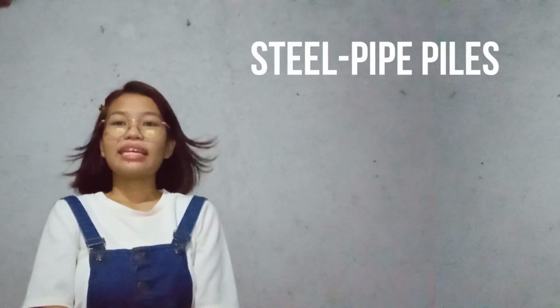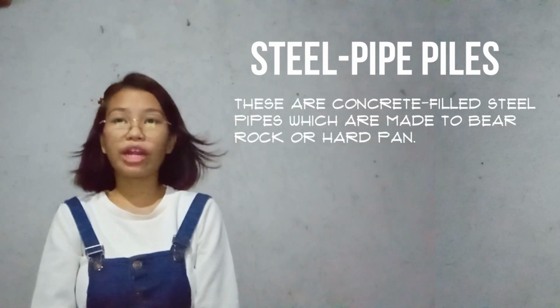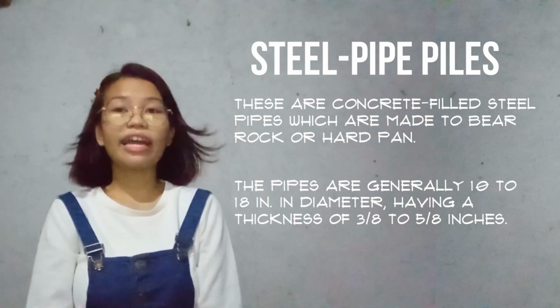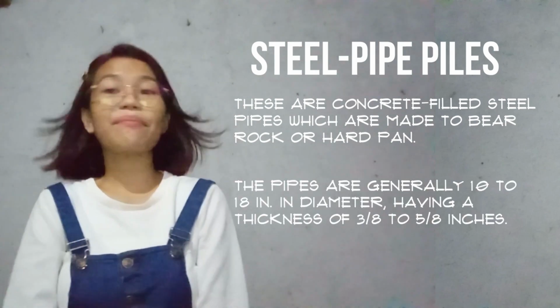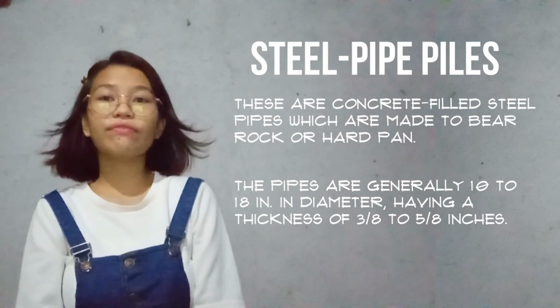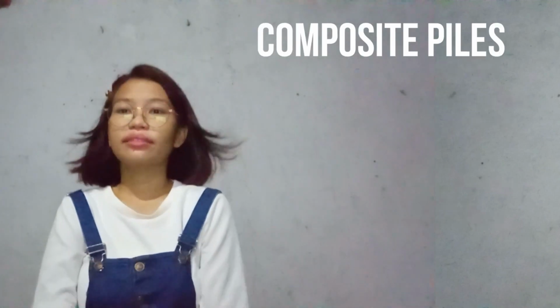Steel piles. These are concrete-filled steel pipes which are made to bear on rock or hardpan. The pipes are generally 10 to 18 inches in diameter, having a thickness of 3/8 to 5/8 inches. Composite piles.